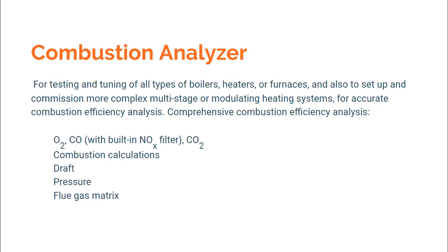It is also programmed. One method is to use these parameters, that is the oxygen, carbon monoxide and carbon dioxide present in the flue gases, and do our calculations using the combustion chemistry to come out with the results. The other is that in all the combustion analyzers available in the market, there is an inbuilt program to do the calculations.